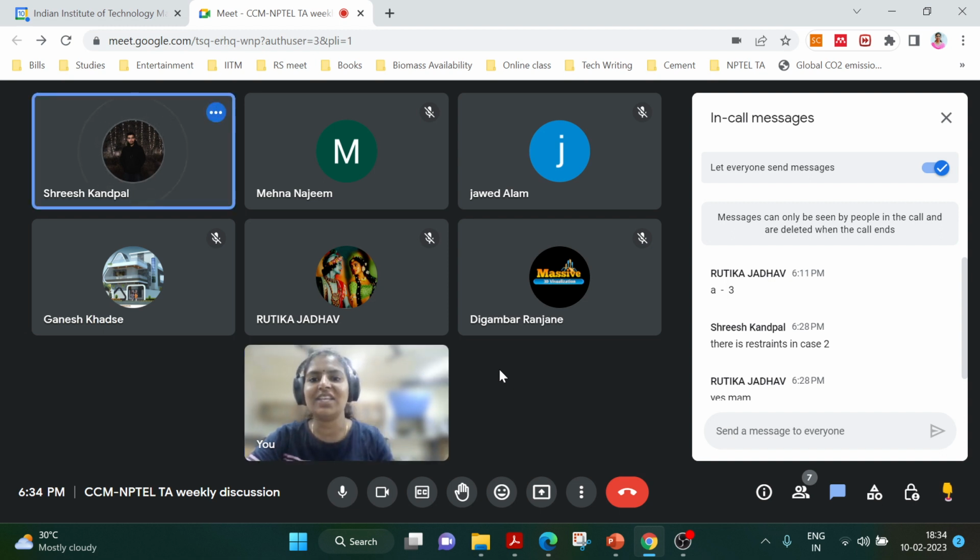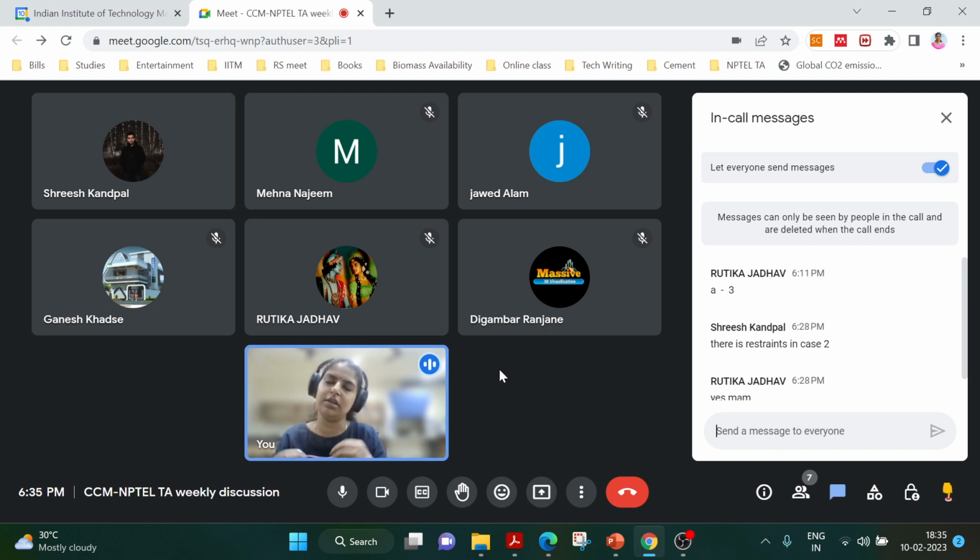Yes, ma'am. Actually, both TMT and QST are the same. But if you take any rebar, it will be thermomechanically treated, right? It will be taken to high temperature and mechanically treated. Then only you can use the rebar. So why do we have to call that rebar TMT? Using QST will be even more appropriate. It will be a better name. It's about how we call it, not about the difference. It's not different. Both are the same. How we are naming it, that is the difference.